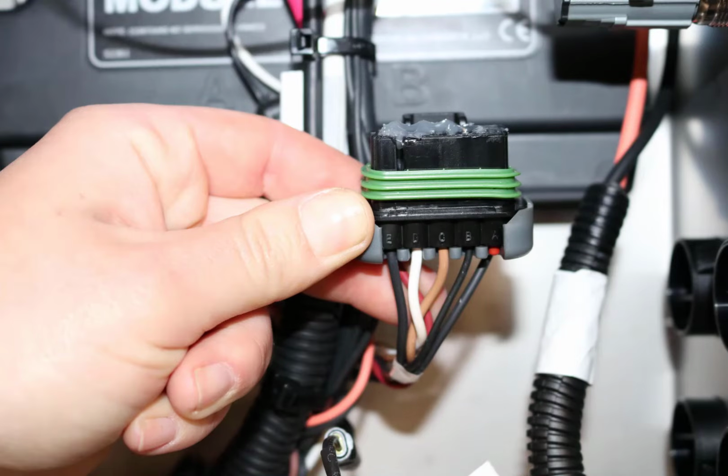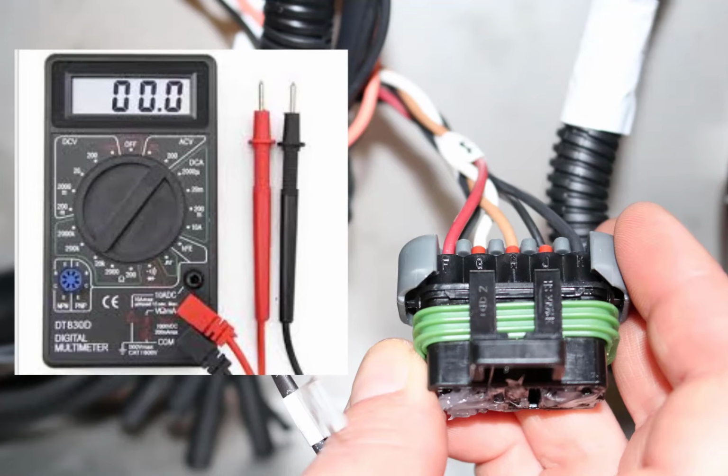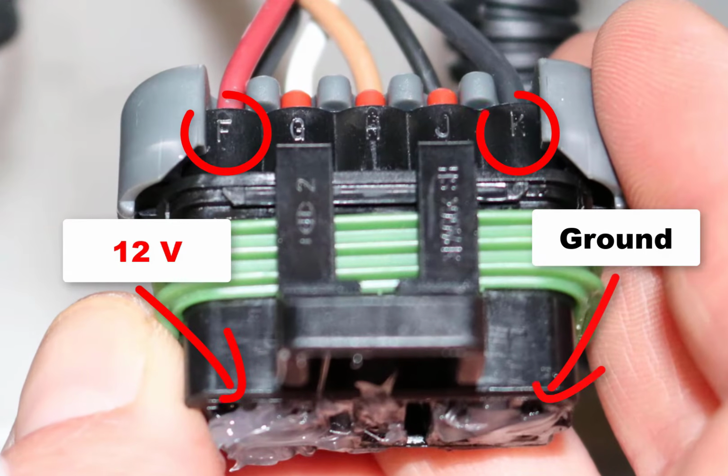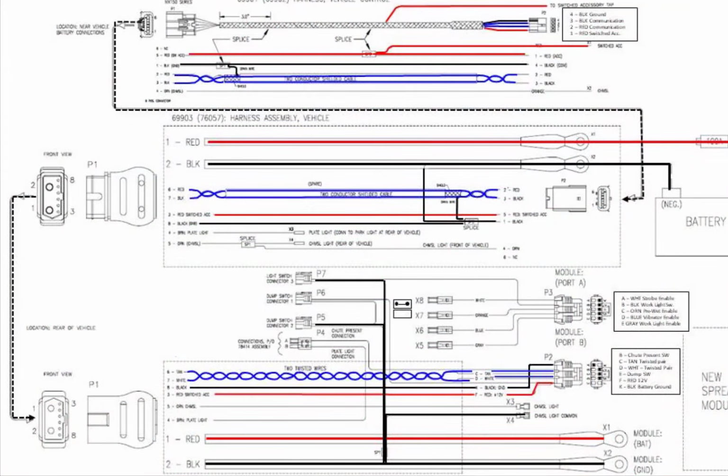Unplug the harness connector at port B of the module, and on the connector end with the key turned on, use a multimeter to check for 12 volts on the red wire on pin F and check for ground on the black wire on pin K. There should be 12 volts and ground present on those pins with the key turned on. If there is no power or there is no ground, back up a connector and check for the proper power and ground until you find where the break is.